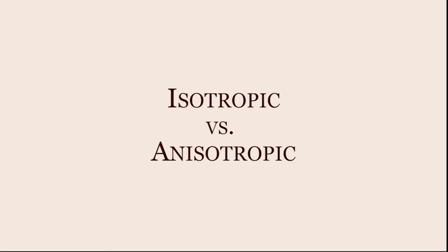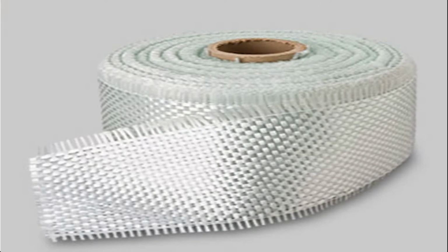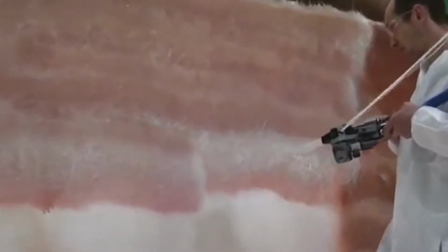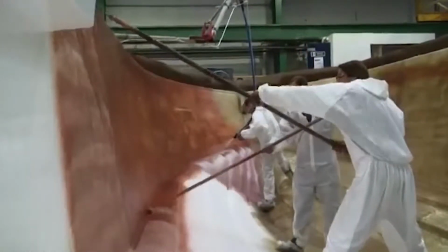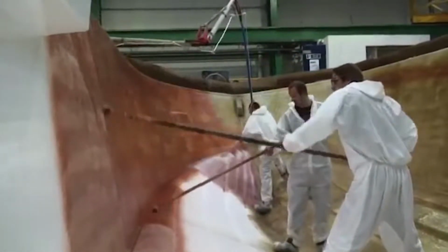Fiber reinforcement. Unlike metals and ceramics, which are isotropic materials, FRP composites are anisotropic, having different physical properties depending on the orientation of the fibers in the composite. Fibers can be arranged in a loose, random orientation called mat, or arranged in a fabric, or in the form of tape. FRP boat building uses fibers sprayed along with resin into molds using machines called chopper guns. Chopper guns spray cut lengths of fiber along with resin in a random pattern into the mold.